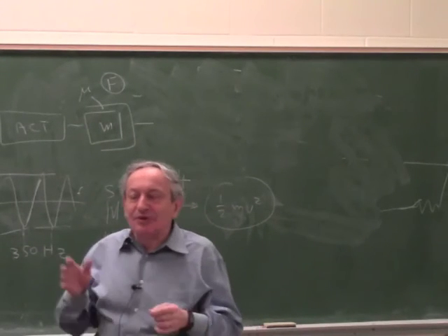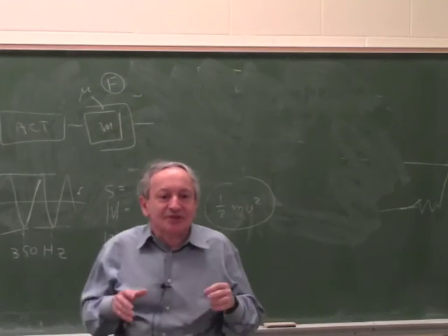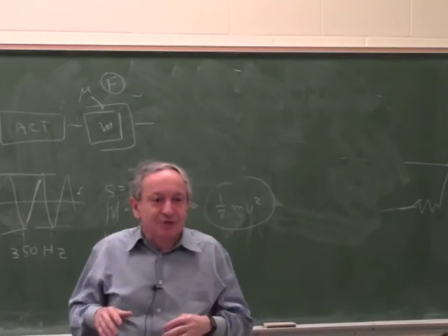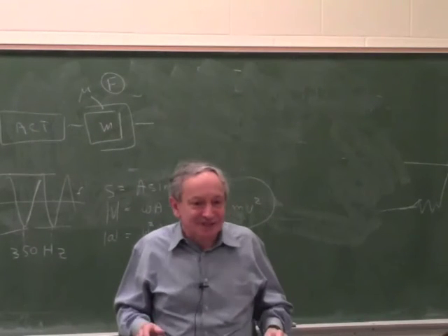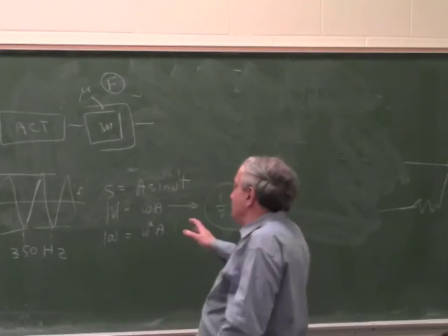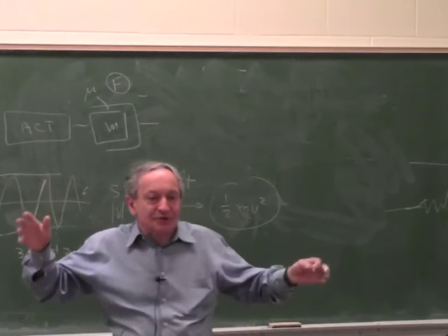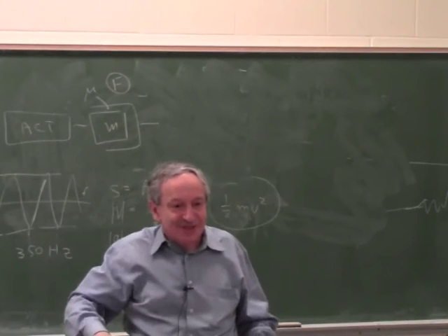But we are not going to go into that, because for most small servos, things are not regenerative. So not just the peak power, but even the average power is there. You have to supply the power, you're not recovering anything. The only reason I mentioned it is that if you design an enormous servo to, I don't know, move bridges or something, then it becomes a factor.